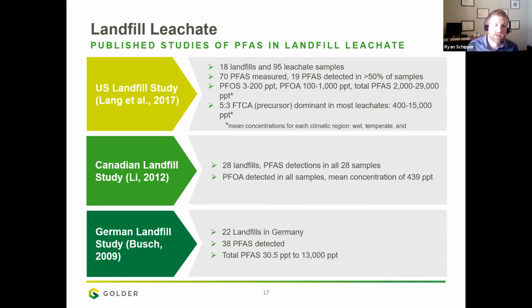There's a Canadian study in 2012. 28 different landfills were sampled, and PFAS was detected in all 28 samples. The mean concentration of PFOA was around 400 parts per trillion, and a German landfill study where 22 landfills were looked at, and there was a number of different PFAS detected in a very wide range of concentrations. So the take home maybe from some of this is that PFAS is in many landfills, if not maybe all of them.